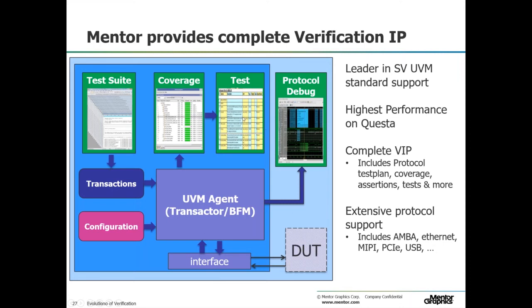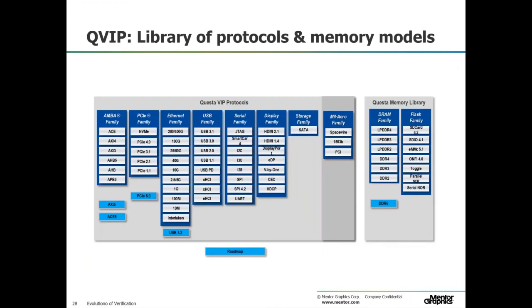We have a full test plan for each of those protocols. So if you want to make sure that you've done certain operations, let's say you're doing PCIe and you want to make sure that the thing operates in Gen 3 and you can send certain types of transactions, you're not necessarily testing the PCIe interface from your vendor, but you want to test that it'll work in Gen 3, that it's hooked up correctly, et cetera. So you can send those transactions, make sure you've tested what you need to, and it's all based on that standard UVM methodology.